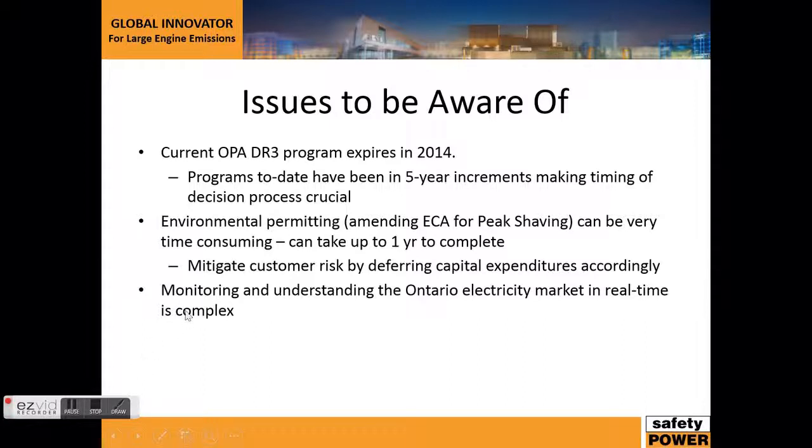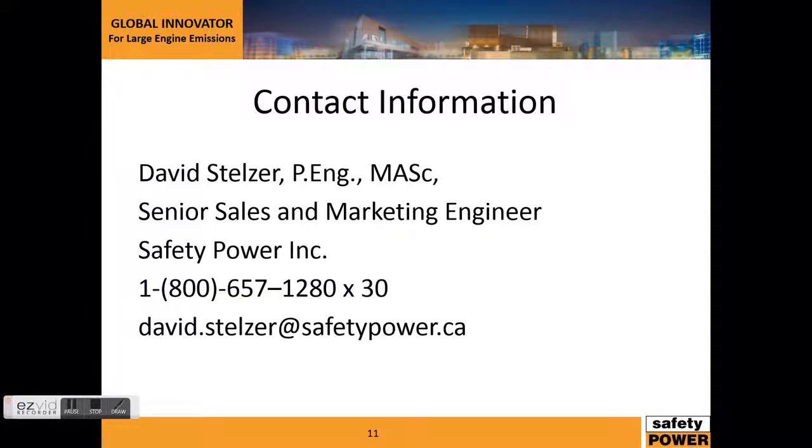Happy to help. The other thing is when you do the global adjustment savings requires you to pay attention to the Ontario electrical market. Specifically, you're going to have to know when the peak demand is getting close to one of those potential 5 hours that I mentioned earlier. And generally they're almost always going to occur in July or August, but it is an added complexity to be aware of.